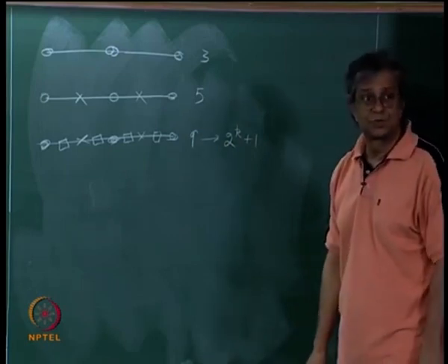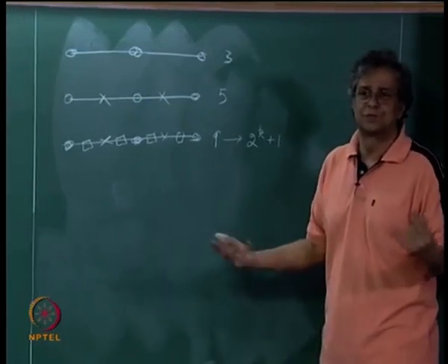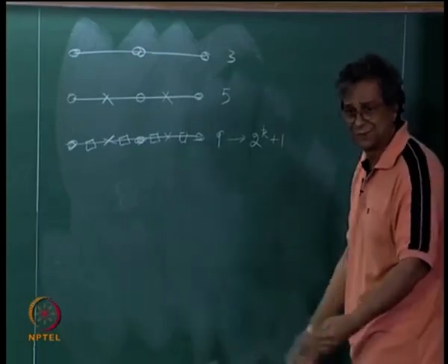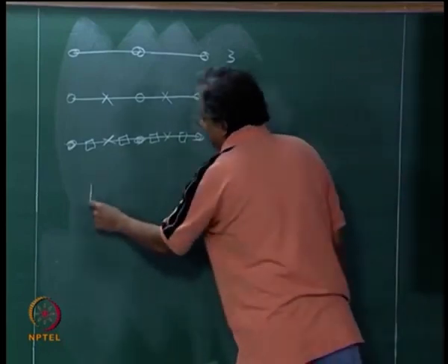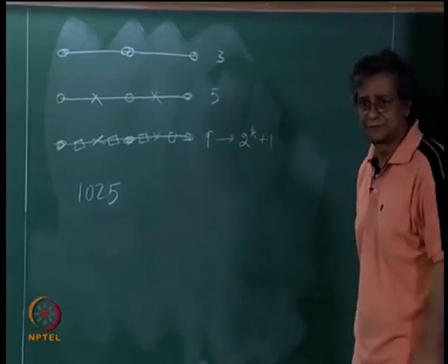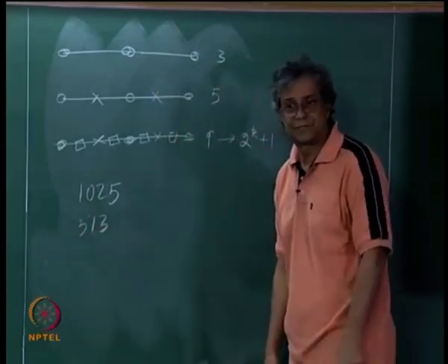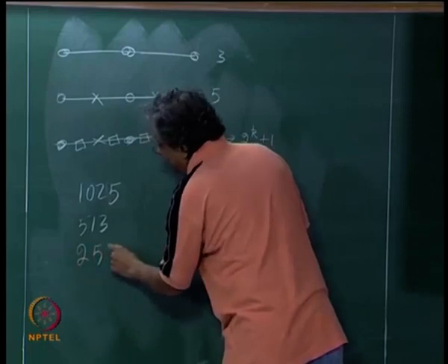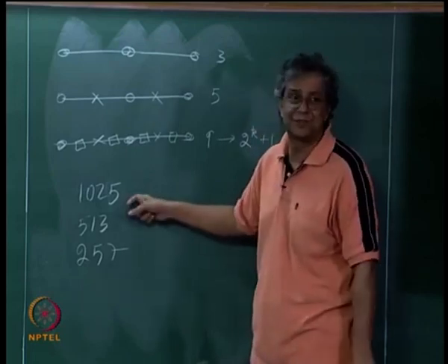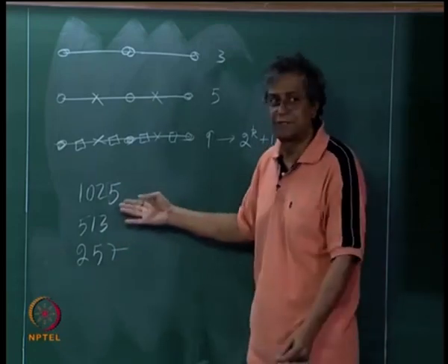So if you wanted a fine grid, I won't start with 1001 by 1001, because that is thinking decimal. I would start with 1025 grids. If I had a 2-dimensional problem it would be 1025 by 1025 grids. As I said, start with 1025 grids and the next level of grids would be 513, you understand, and 257. Now you understand why you need to go to multiple levels. This is 257 grids, this is still pretty fine. It is just that if it is 1 meter length, we want the answer on something of the order of 1 millimeter. Okay, 1025 is close enough.